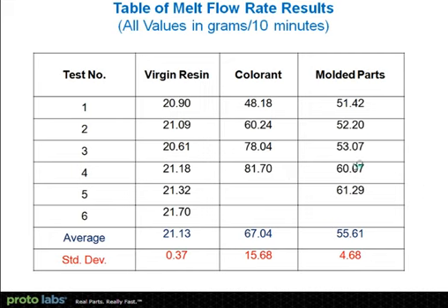And some of that instability has actually been communicated to the molded parts by virtue of the fact that the concentrate is being mixed in with the base resin. So the color concentrate is definitely a component of the problem.